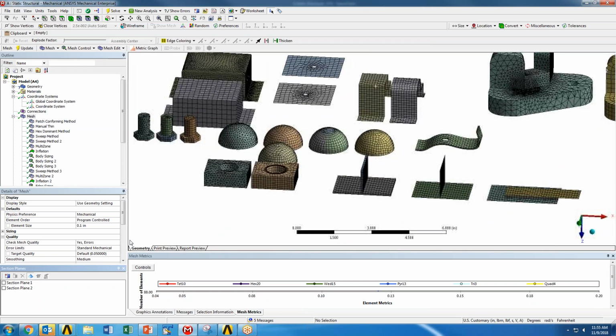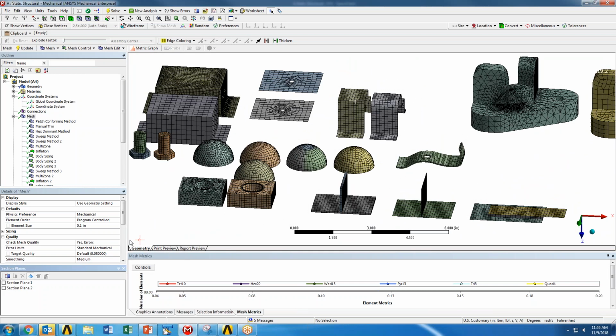Let's see. So I know that's a whirlwind, but that's general control and general recommendations, right? Honestly, the largest recommendation I can make with regards to meshing is to very heavily focus your time on preparing the geometry rather than just immediately taking the geometry and meshing it, right?